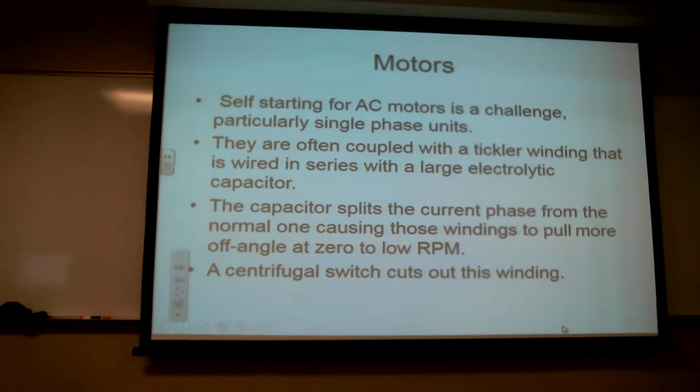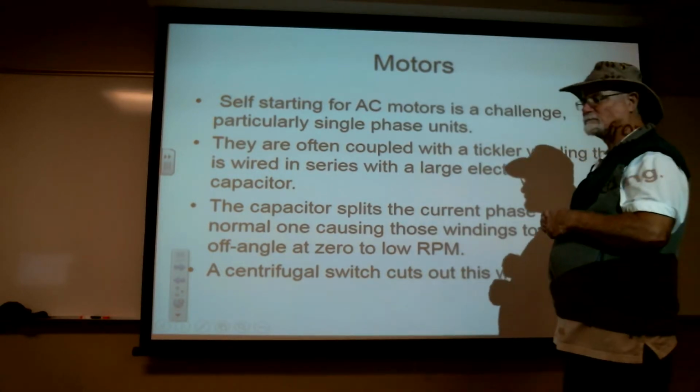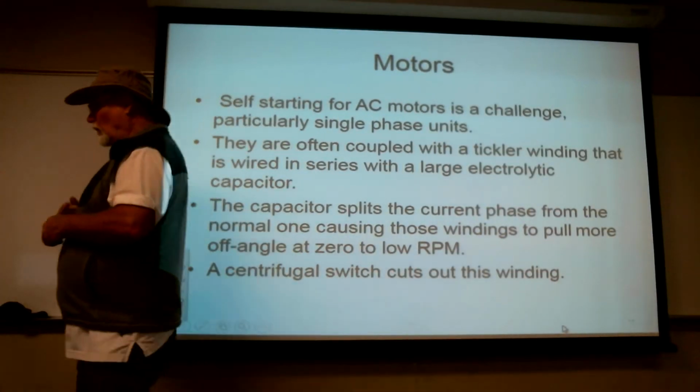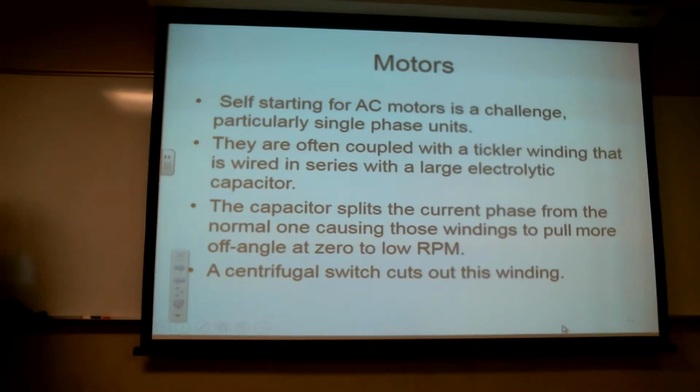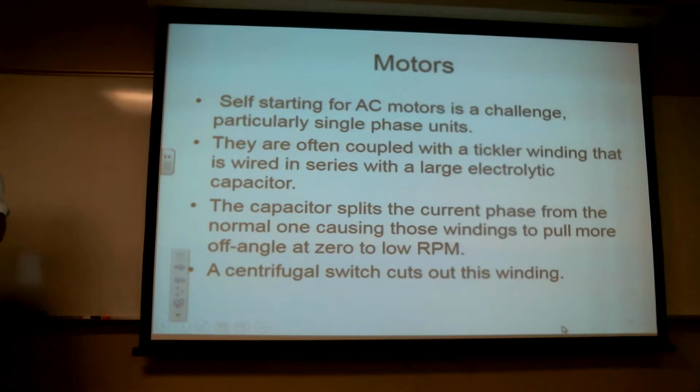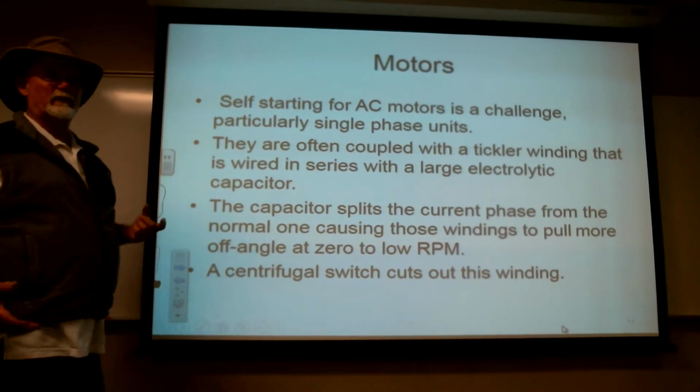So you know, all the AC motors you see, bigger motors, have a big bump on the side. That big bump is the capacitor. Okay, that big capacitor is a starting capacitor, and we use it just to distort things a little bit. Now this is one way to do it, and it's a fairly powerful way of doing it. It also helps produce a little bit of extra torque, so that actually helps a fairly large motor get started.